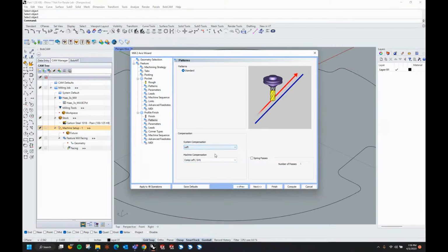In my last shop, I actually used both. So I would program for a 3/8 diameter mostly to cut out my parts. And if I had to change the tool mid-job, I would just throw in a reground tool, and I might have to adjust my compensation in the machine negative the difference from the original size. So if it was 15 thou smaller, I would just do -15 in the control and it would offset and I wouldn't have to reprogram anything. That's a really handy setup for wear comp if you're using the same diameter tool all the time. But if you're changing diameters constantly, you're better off probably just using G41 comp by itself.